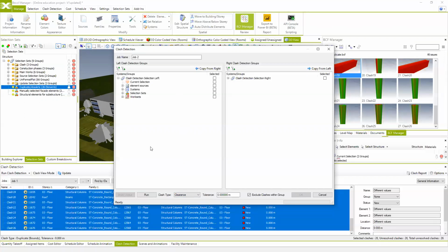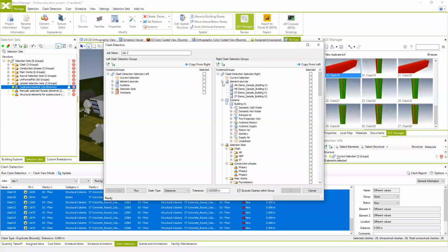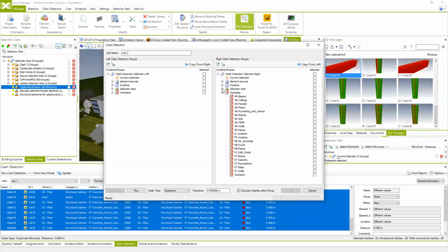And also, the common way you specify which type of element will be checked for a clash with another type of element is the place where you're specifying that, here. Right here, the system shows you all automatically segregated BIM model elements.